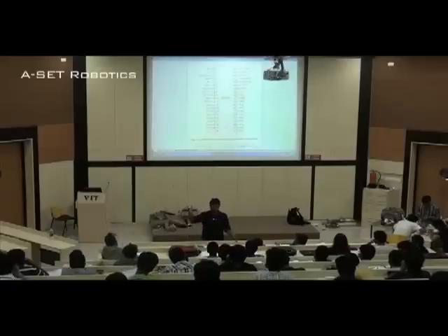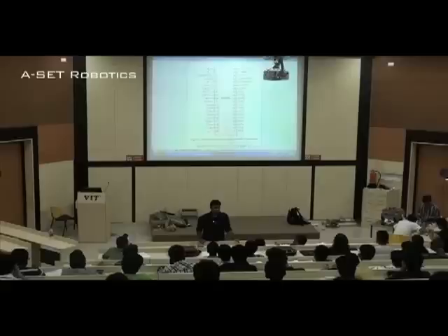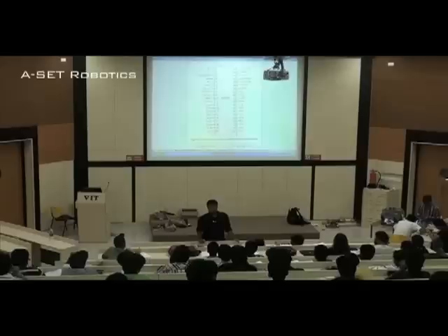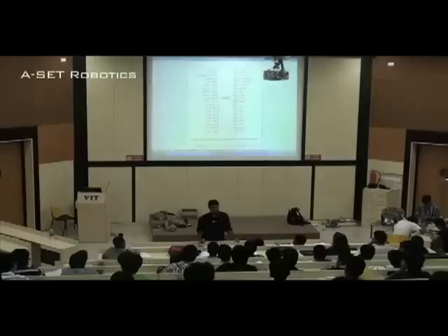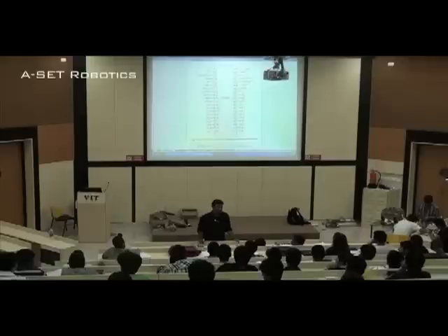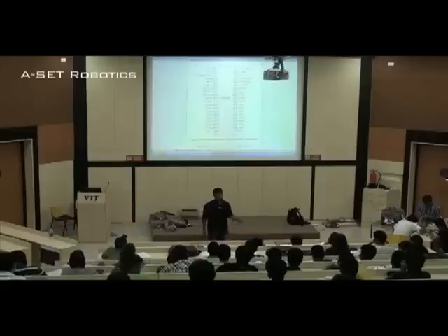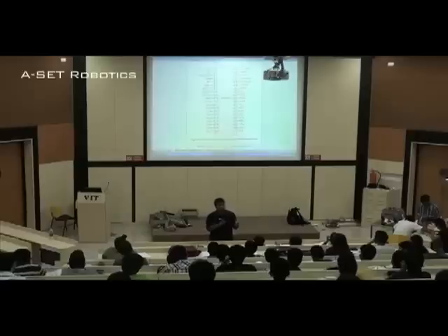For example, if we reduce the number of address lines from 16 to 8, what would have happened? Then how many memory locations can it handle? Can anyone tell me? 256 memory locations. Do you think it is a big space? It's not a big space. So because of that, we need to multiplex it.